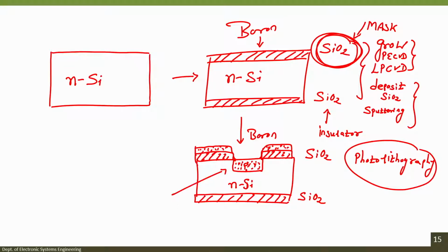The boron at the surface will become boron oxide. So, this boron oxide and silicon dioxide we have to etch. This silicon dioxide and boron oxide at the surface of the silicon we have to remove. Removing is etching, so we will use buffered hydrofluoric acid, BHF.